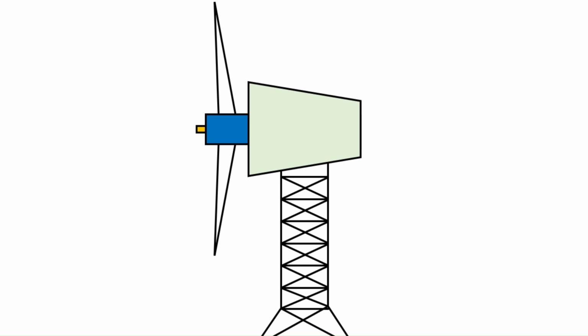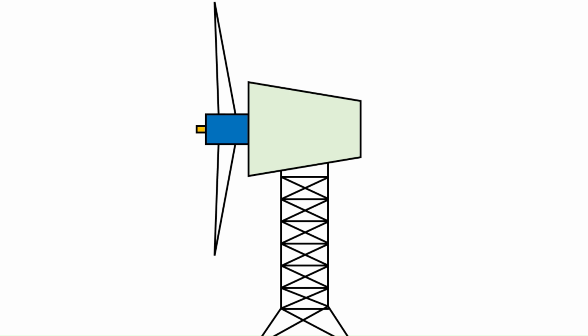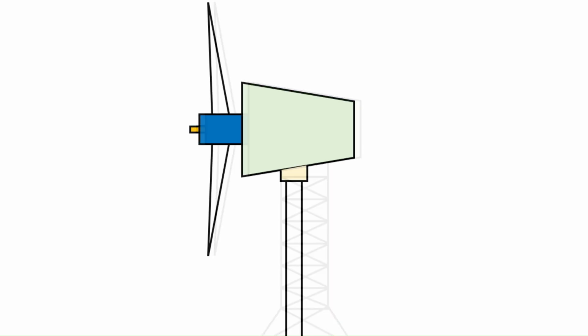As the load is distributed over a wider area, this tower requires a comparatively lighter foundation, which will again contribute to the cost reduction. The major problem in lattice tower is it is not good looking because it is visually unacceptable to some viewers. Similarly, avian activities are more intense around the lattice tower because birds can conveniently sit on its horizontal bars. This may increase the rate of avian mortality. Due to these limitations, most of the recent installations are provided with tubular steel towers.